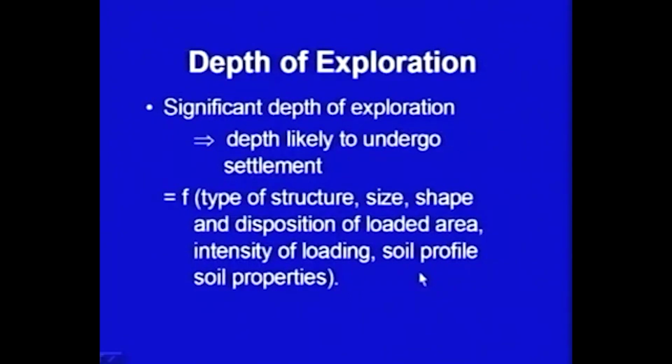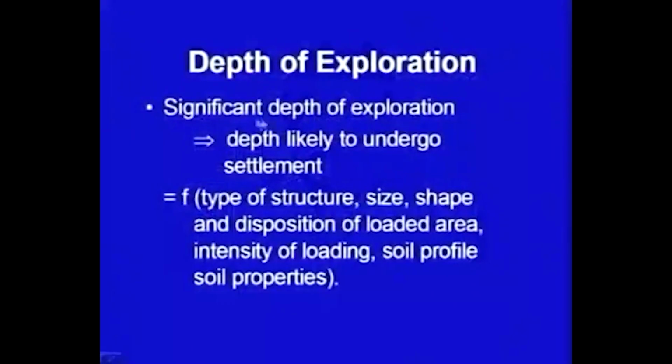Now, let me talk about what should be the depth of exploration. This is the thing which you have to decide when you plan for the detailed investigation. One basic thing which we have to keep in mind is the significant depth of exploration, that is, the depth which is likely to undergo settlement.